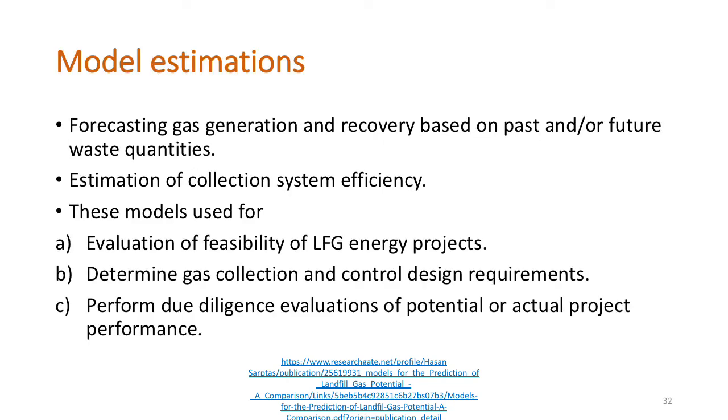Model estimation. It is the practice of forecasting gas generation and recovery based on past or future waste quantities. These models are used for evaluating the feasibility of LFG energy projects, determining gas collection and control design requirements, and due diligence evaluations of potential or actual project performance.